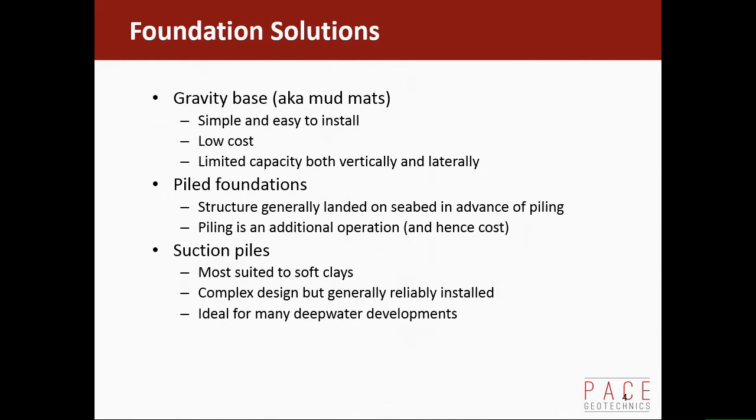There are three main types of foundation, and pretty well all seabed offshore structures fall into one of those categories. Gravity base, also called mud mats. The big advantage is you basically land your structure on the seabed and that's it, done. So it's obviously much quicker, it's easy to install, it's low cost. The big disadvantage is the actual capacity is limited, particularly on soft clays. Your vertical capacity and your horizontal capacity is limited.